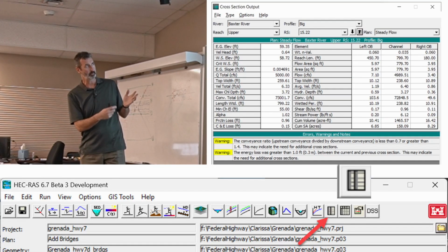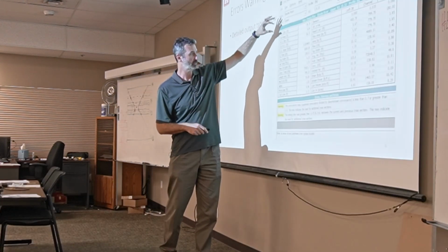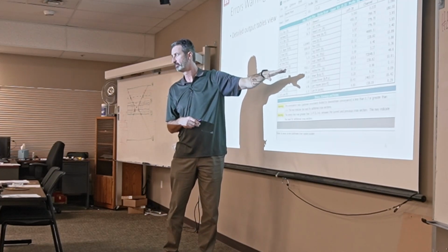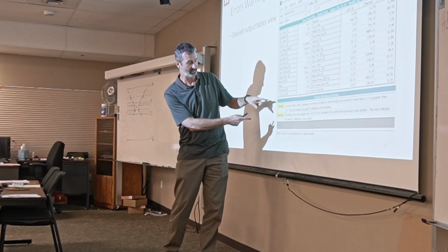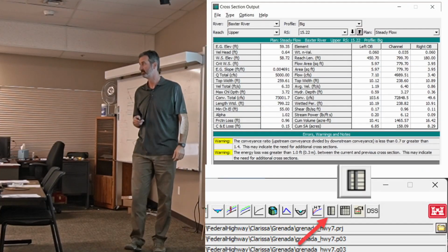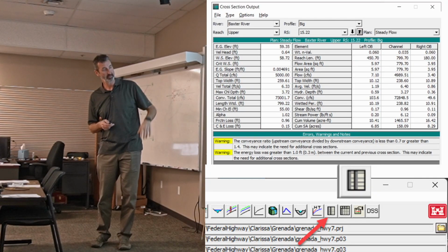On the node-specific table, which I think we came in here for the culvert one, we were in type culvert, and one of these messages down here said it was inlet or outlet control. So that's all of that table data, but down here on the bottom it also has those messages for this location for that profile. That other table we looked at was like all of them, but here's kind of a detailed, zoomed-in look at that.